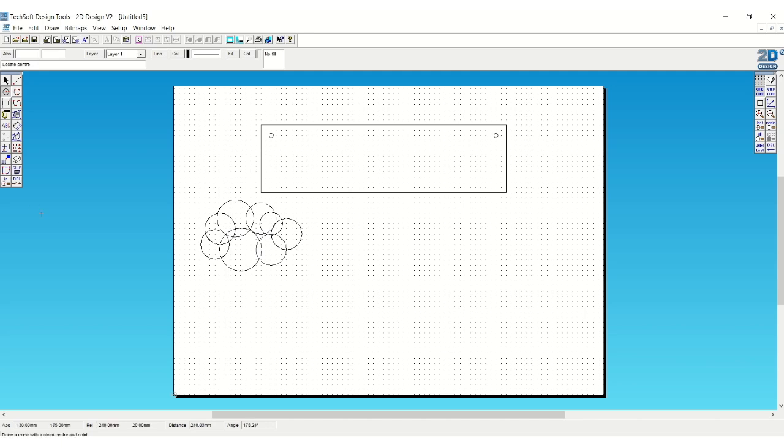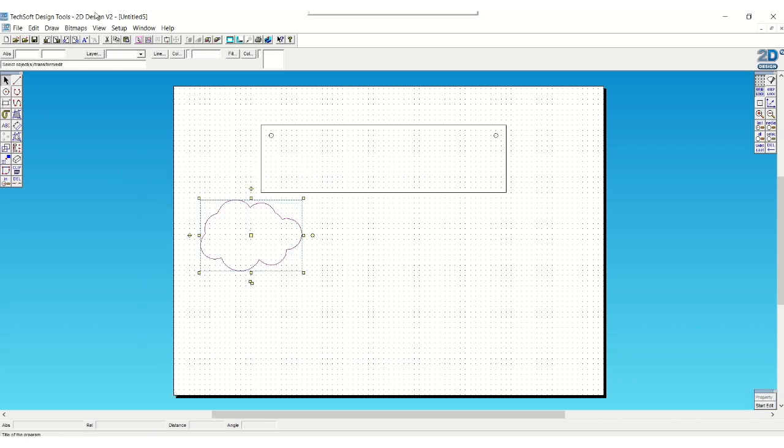Then I'm going to pick the delete tool. Make sure you've got the one with the gaps, then you can click intersections and delete them. And now I'm clicking everything away to delete until I'm just left with the outline. So that's done now. Now I'm going to select the whole shape and use the group tool at the top, so now I can edit that as a group. It's going to be much easier.